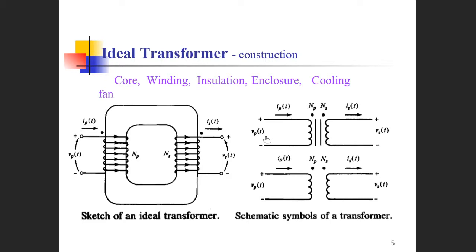Okay, in electric schematics, you can use different symbols to represent transformers. Using the symbols we draw here on the right side of this slide, the dots indicate the polarities of the two sides. That means, in the circuit, how to connect the transformers correctly.